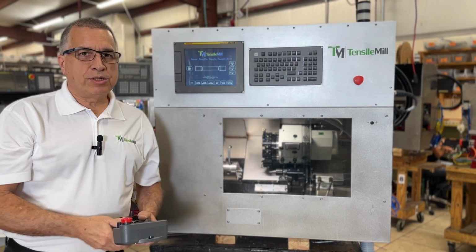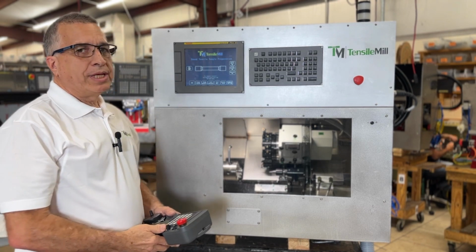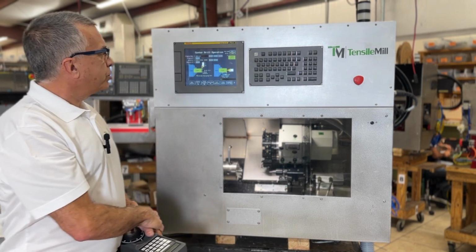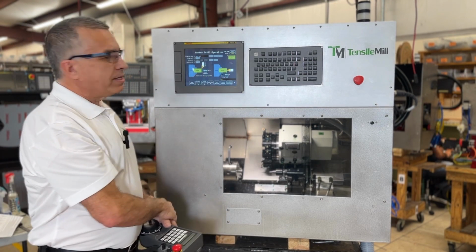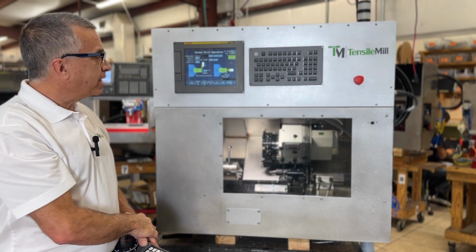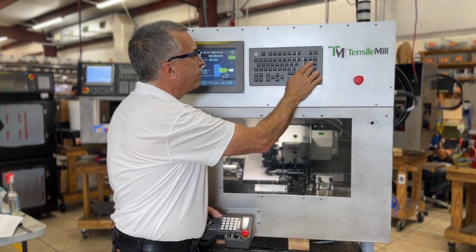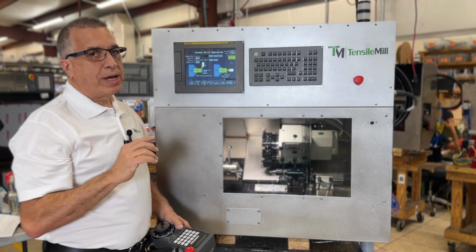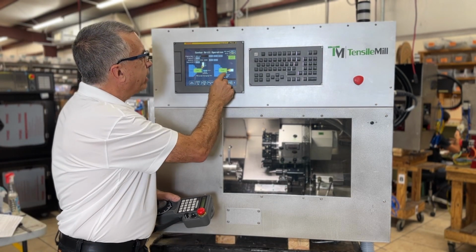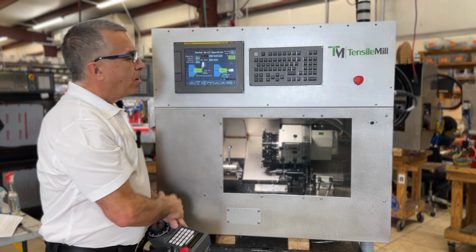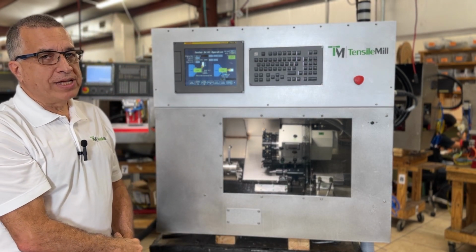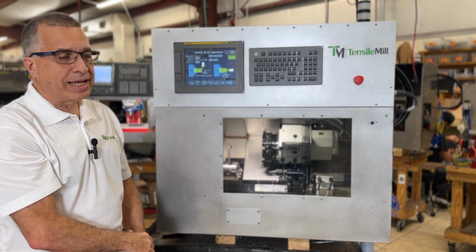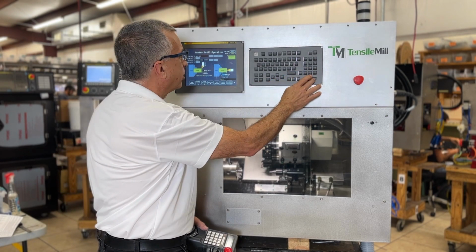Okay, once we finish programming the part, we're going to program the center drill. We just choose the center drill operation. We need to specify the diameter of the blank, in this case 0.625. We need to tell it to include facing, otherwise it will just do the center drilling. And then here we specify the length of the face of the part, the blank, from the chop. So we have to set that same length, in this case, 1 inch.